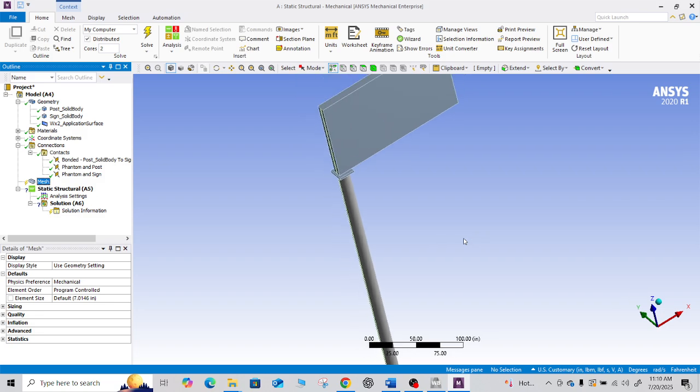So mesh, I think you know that we divide the section. Actually, in MATLAB, you see that we have divided the length into nodes, and also we have taken the square matrix and divided it into some sections. So this is basically that we're going to divide this whole geometry into small sections, and onto that we're going to perform the analysis. We're going to apply our differential equations and perform with the boundary conditions, and we're going to solve it. So we have to discretize this geometry into some sections. For that we have to use the mesh.